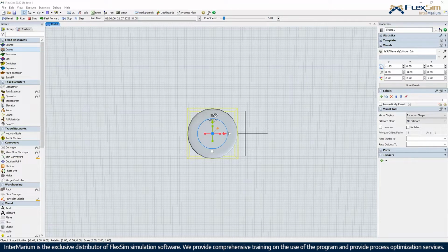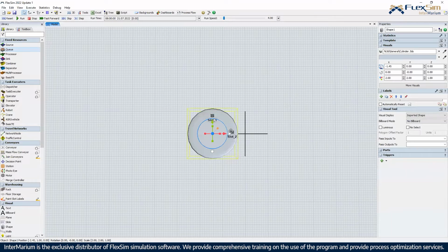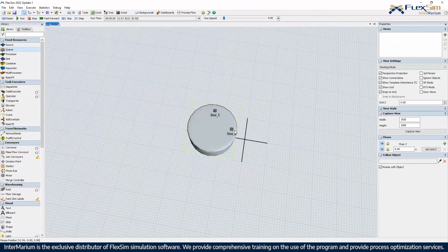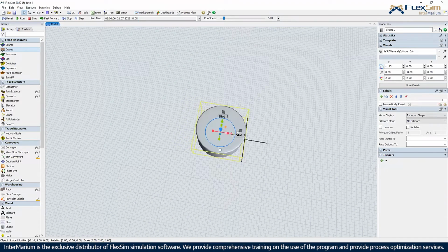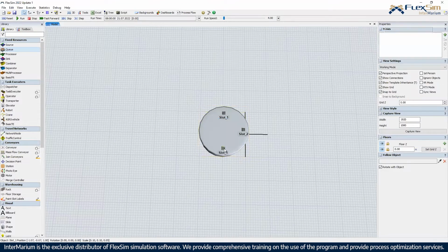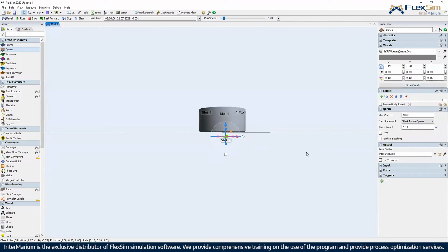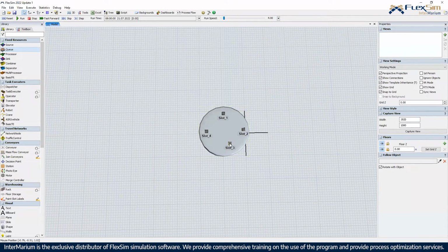So click on the slot, Ctrl+C, click on the shape, and Ctrl+V. So now, as you can see, this slot is also part of the table. And also the naming is okay. When I copy it, the number at the end just increments. So I have slot number 2. Oh, I didn't click on the shape, sorry. So now slot 3, click on the shape, Ctrl+V, slot 4. I will lift this one up. Okay, so we have 4 slots on the table.